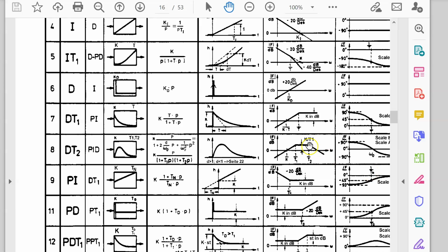And the idea is correct, but finding a good controller type is not so easy, because here you see the D is an indication for differentiation, and in the phase curve you see that there is a part in the frequency range where we have a large positive phase. So could we use an acceleration by these blocks?